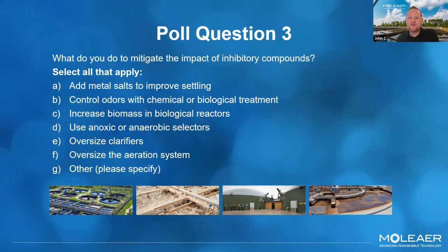Looks like the majority of you answered increase the biomass in biological reactors. And that is, in fact, the most common way that we deal with it, is that the more biomass that we have, the more that we can ride through the shock loads that come into our treatment plant. Very interesting.